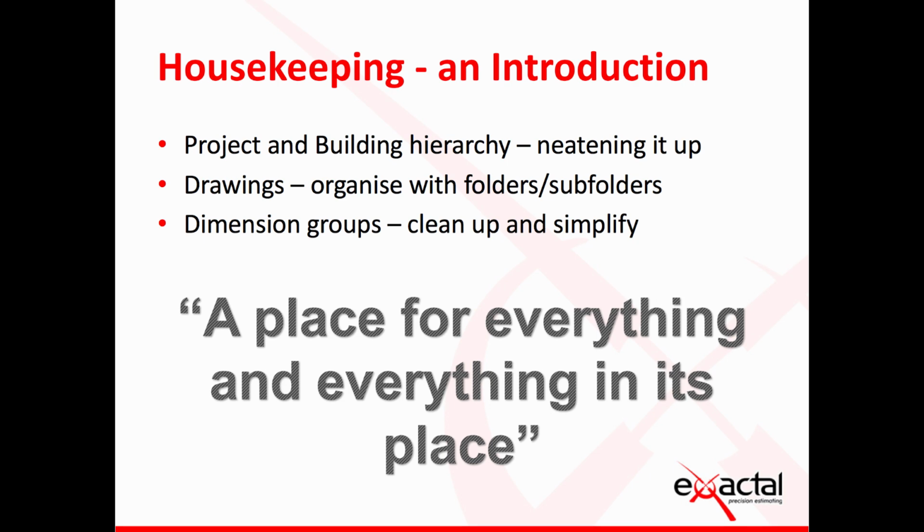The items that I will be discussing this month, first and foremost, is the projects and the building hierarchy and how to neaten that up. Next, I'll touch on the drawings, how to organize them with folders and subfolders, as well as renaming and utilizing the CostX built-in drawing register. And then I'll also show you the dimension groups and how to clean them up, simplify them a bit, with the emphasis on our one-to-many relationship, as we call it, meaning that one dimension group can be linked to many items in your bill of quantities or your workbook, as we call it.